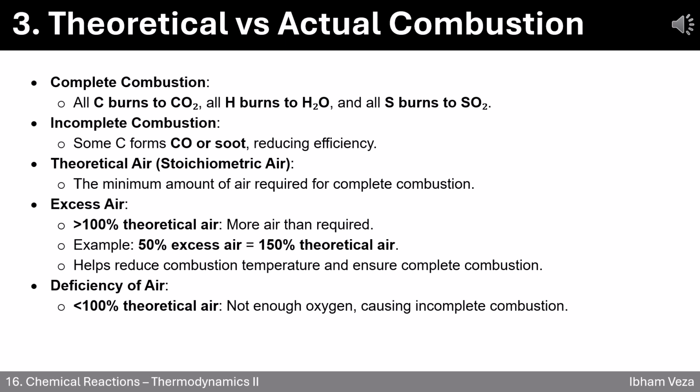That's where the concept of theoretical air comes in. It's the exact amount of oxygen needed for complete combustion. However, in real systems, we often use excess air, more than 100% of theoretical air, to ensure full combustion and reduce harmful byproducts. For instance, 50% excess air means we supply 150% of the required air.